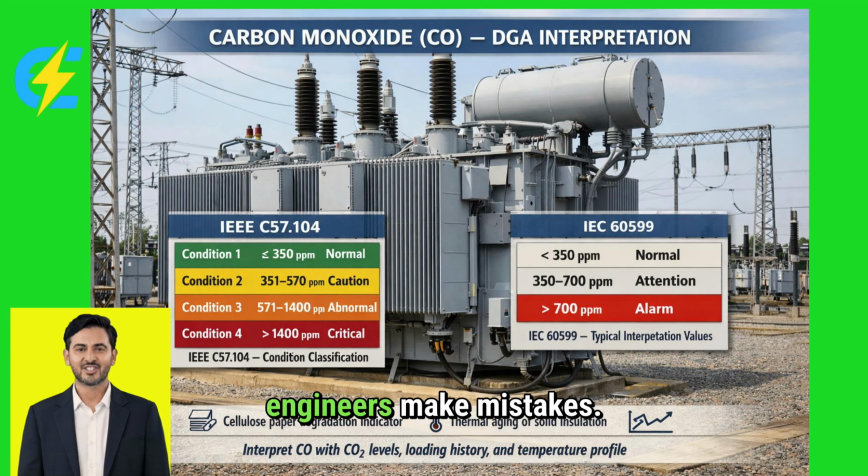But here's where many engineers make mistakes. They look at a single carbon monoxide reading and try to make decisions based on that number alone. The trend of carbon monoxide over time is far more important than any single ppm value. A stable, moderately high carbon monoxide level in an older transformer might just indicate normal aging. But a steadily increasing carbon monoxide trend, that's telling you about accelerated paper degradation or thermal stress that needs your attention. Let me walk you through the different scenarios you'll encounter.